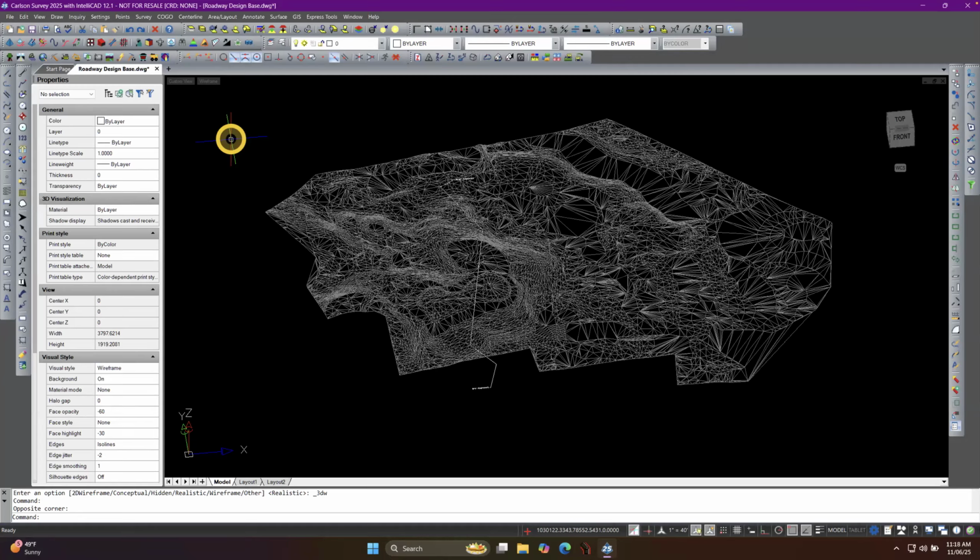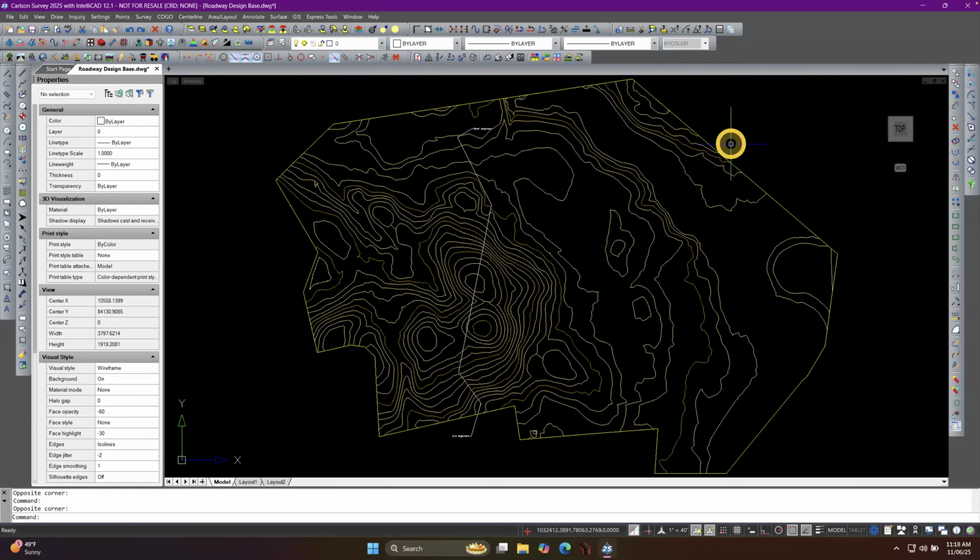In this case, it would be a bunch of lines that draw it as a triangle. If I explode that block, it would be the drawn polylines, and then exploding that block takes it into each individual piece. Each of those little pieces of lines that make up the contour lines, it basically takes down to its simplest level, at which point you could use that to define your surface, et cetera.